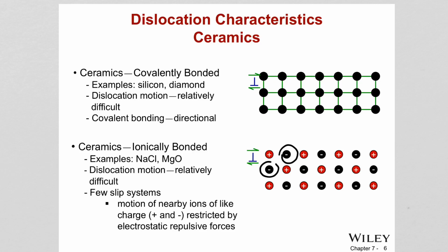But of course they will repel each other, and this also creates a small number of slip systems, deformation systems basically, and it makes dislocation motion more difficult in ionically bonded structures. It requires more energy, more stress.